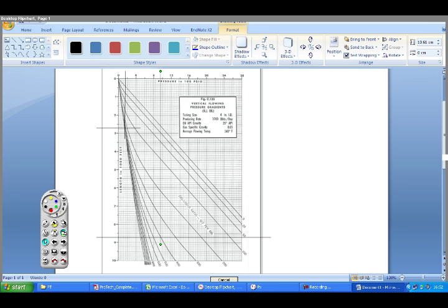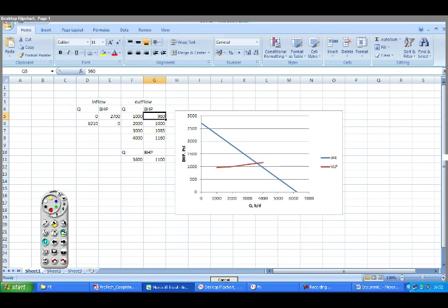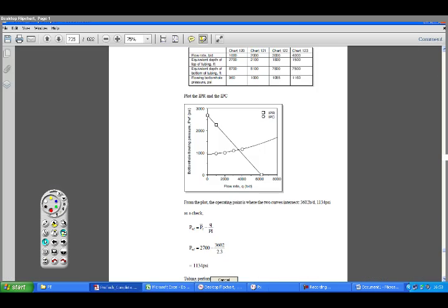You have to find your equivalent depth for your particular GOR curve. You have to measure down your tubing length, and the value of your GOR curve at this particular depth will give you bottom hole pressure. Finding these bottom hole pressures for different rates using different charts, you will be able to plot your outflow performance relationship, and the intersection point will give you the solution. Thank you.